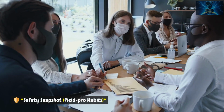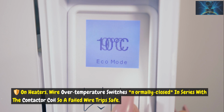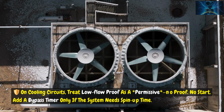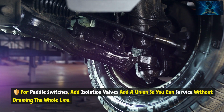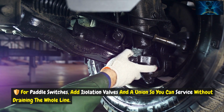Safety snapshot. Field Pro habits. On heaters, wire over temperature switches normally closed, in series with the contactor coil, so a failed wire trips safe. On cooling circuits, treat low-flow proof as a permissive: no proof, no start. Add a bypass timer only if the system needs spin-up time. For paddle switches, add isolation valves and a union so you can service without draining the whole line.